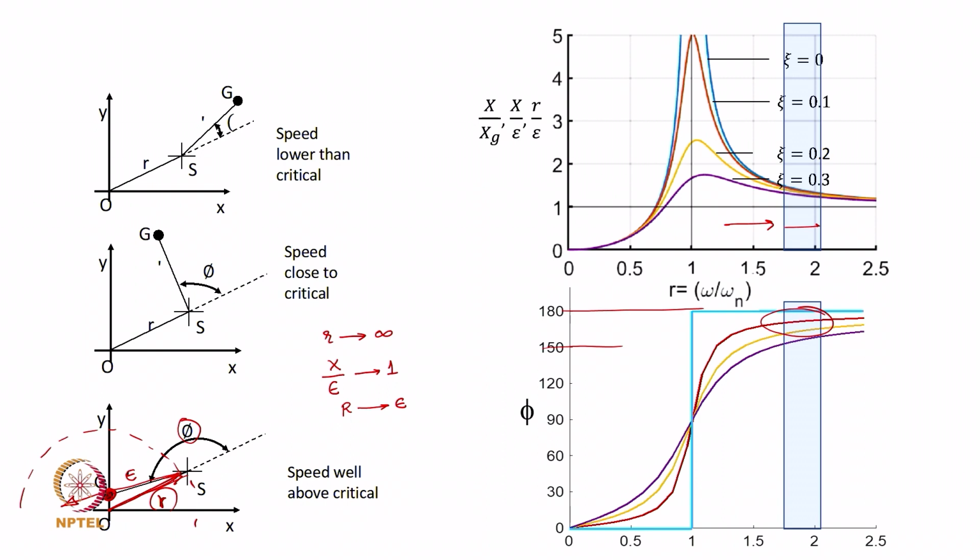So, what happens is that the rotor is actually whirling with the mass center close to the bearing axis, and so you basically have the entire vibration whirl motion with an amplitude close to the unbalance eccentricity. And it actually turns out that if you try to reduce the eccentricity value, your response amplitude becomes 0 or close to 0.